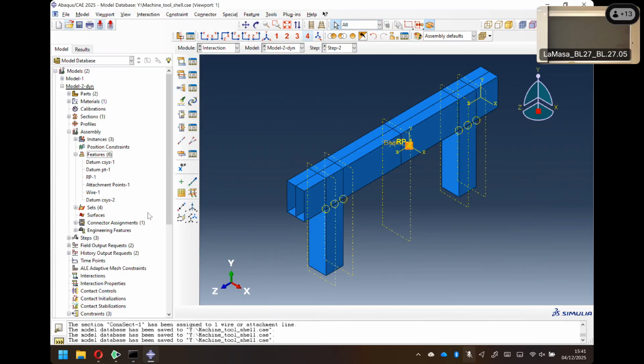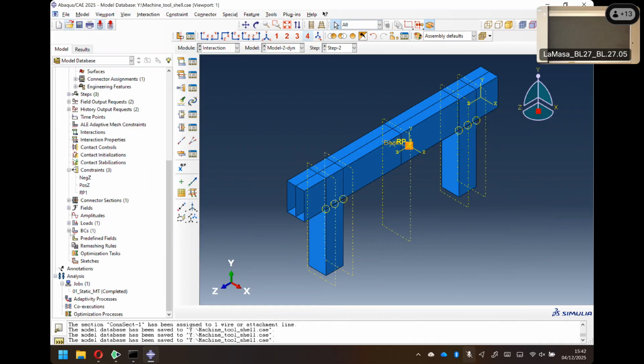The coupling was made just like before. So we have basically the same simulation as before. We just apply the mass of the spindle there. We ask for a quick frequency analysis. Boundary conditions, are they still there? Let's check. Yes, of course, because it was created in the initial step. Loads, is the load still there? No, it exists, but it was suppressed because its step was suppressed.